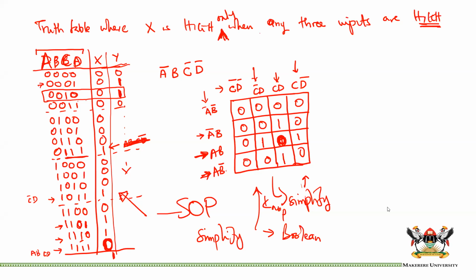I don't even understand what you have just said. We only need a sum of products if we are going to use Boolean algebra. If we are going to use the K-map, we don't need to formulate a sum of products form. You can do it, but it is not really necessary, because we have seen that we can go straight from the truth table into the map without first looking at a sum of products. This statement is NA3, not only 3.